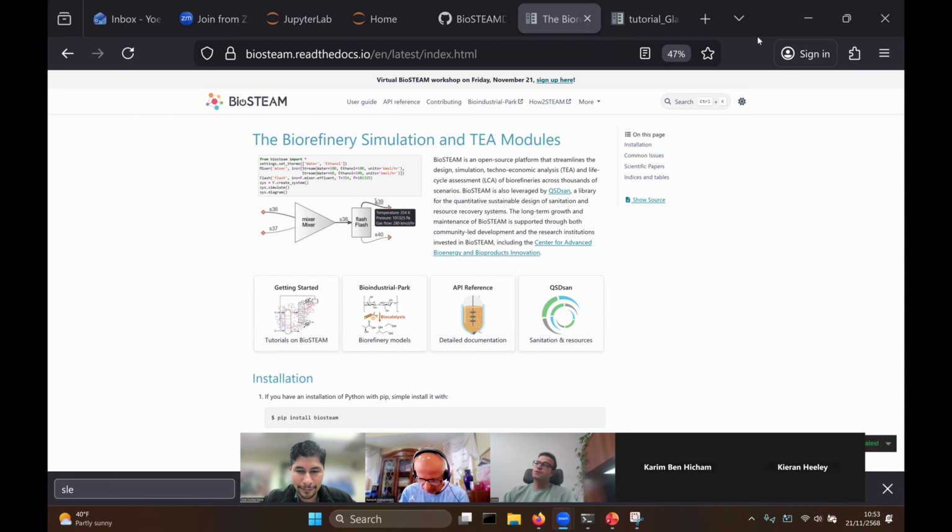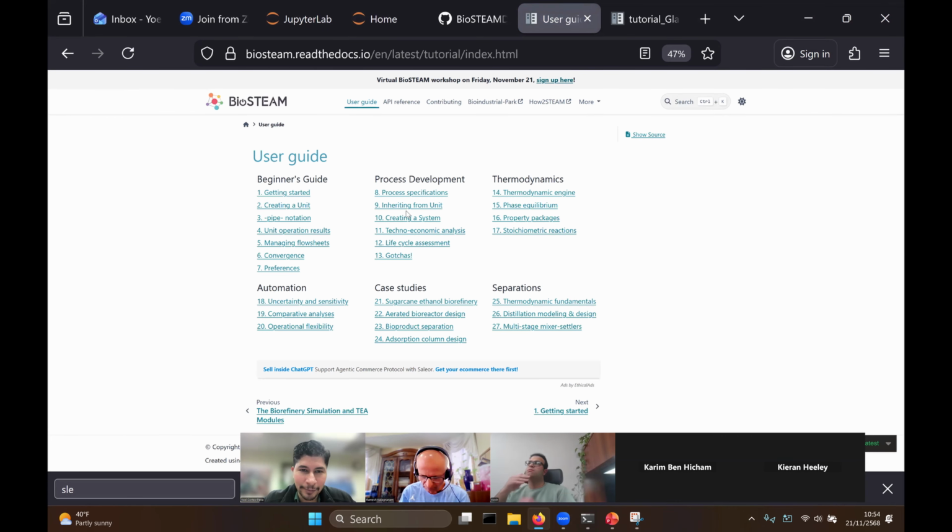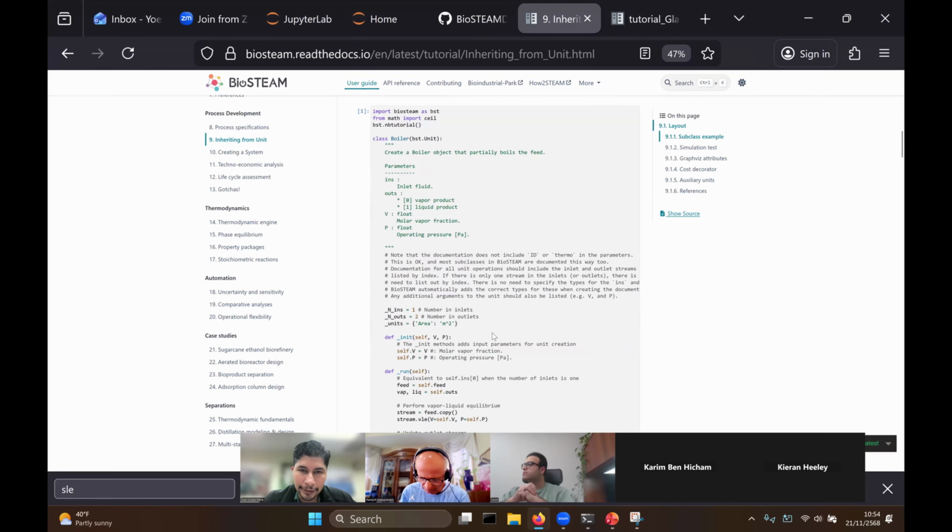It was very helpful. My question is: is there any option within BioSTEAM to change the fixed cost associated with each of the equipment? Yes. It's not quite an option, but it's not that complicated. You just need to be a little bit familiar with Python. One thing you can do is subclass from unit operations. Even a distillation column, for example, you can subclass from mesh distillation.